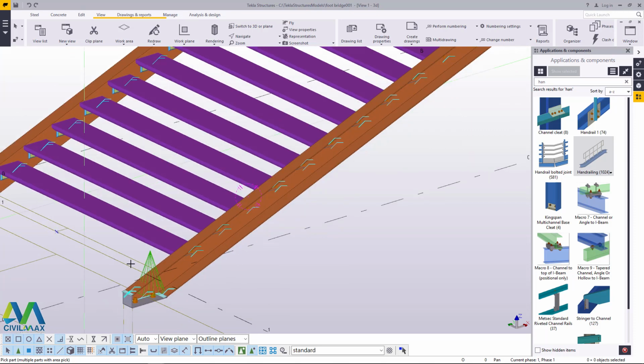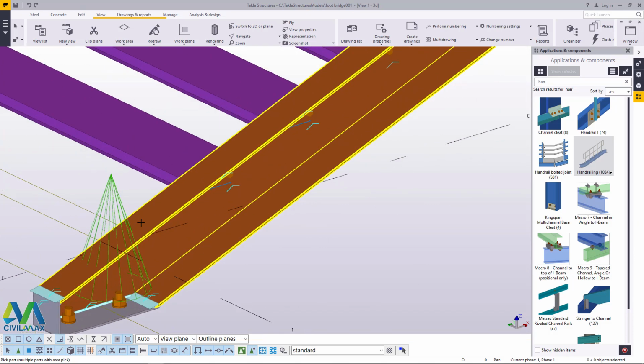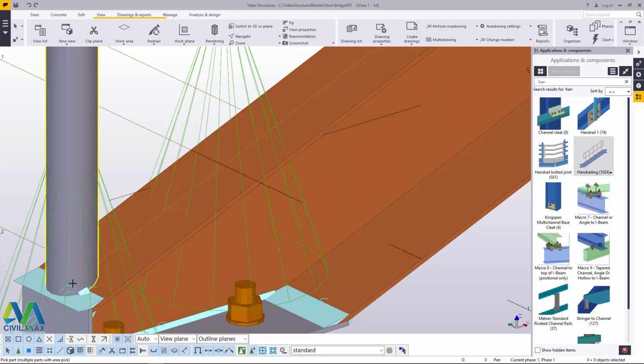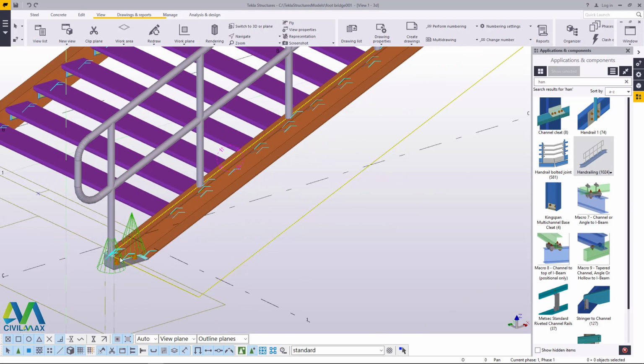Now what do we do? This is the point that we need. Do we really need to mirror it at this point? Not really. And I will just come here and click on that and place the position. We can read at the bottom end here, pick the position where you want your handrailing to start. I want it to start at this point right there, and you can see the post right in place. Right click and click interrupt, and this is what we have.